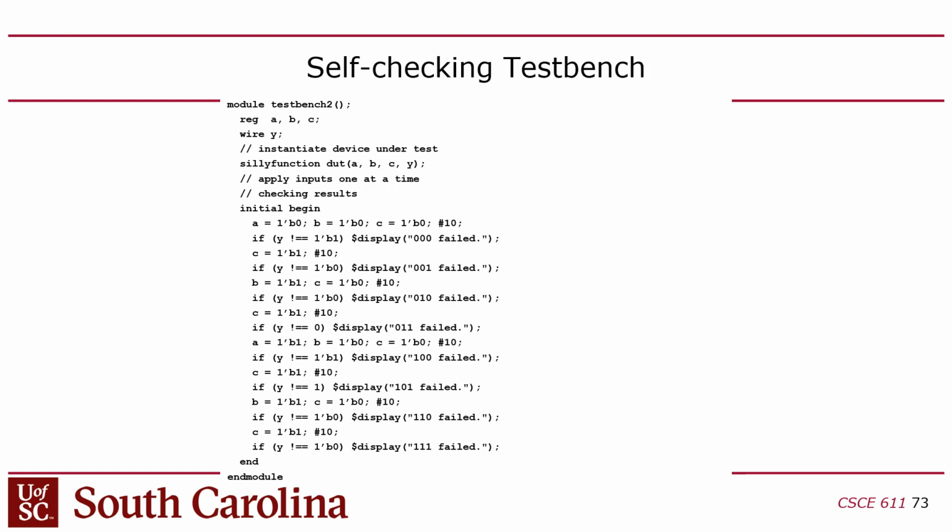Now I've got this little function I'm calling called $display. Now $display, I think you can synthesize code with that in it, but that would just get ignored in the synthesized code, because $display is designed to print a message to the simulator console. There's no simulator console if you put this in hardware, obviously. This is only for simulation, okay?